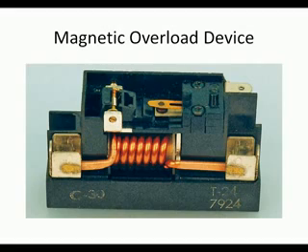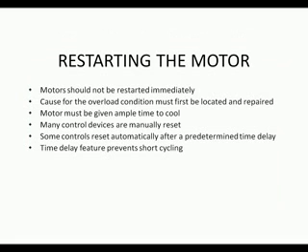Magnetic overload devices are accurate means to provide overload protection as well. The device is not attached to the starter. The device is not affected by increased ambient temperatures. The contacts within the device will open to de-energize the motor at an amperage level, not heat.